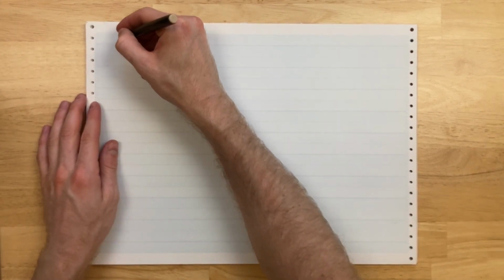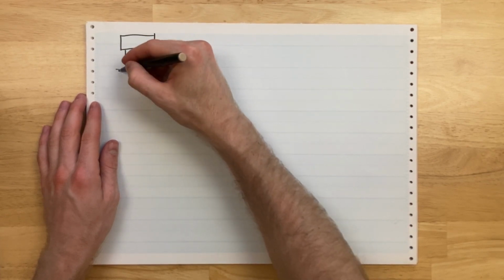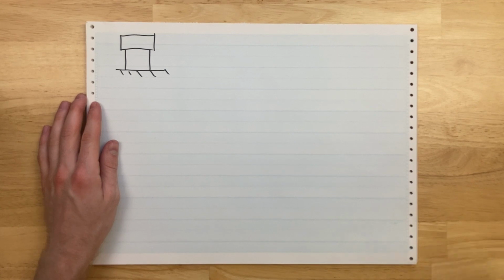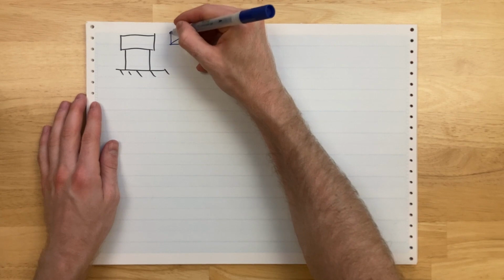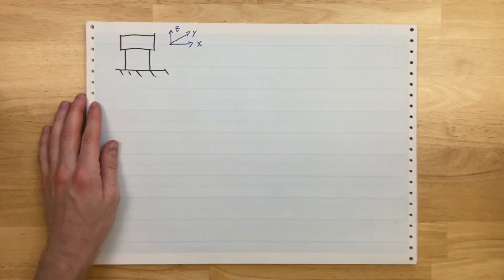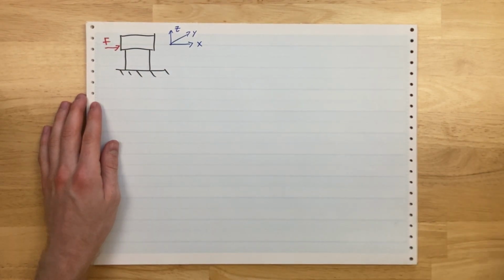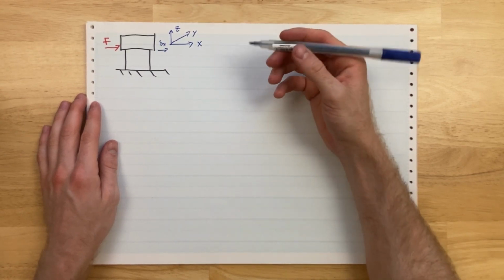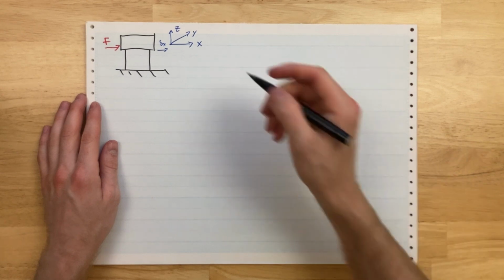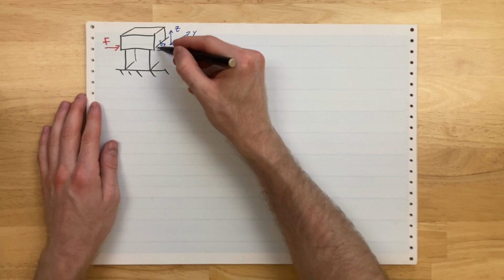So what is the parallelogram flexure? I have a bar. That bar has 2 beams. Those beams are on a fixed base. And I take my coordinate system. It moves in X. Y is out of plane. Z is vertical. And if I push on this with a force F, I find that it will move a distance delta X. And if I look really carefully, or if I actually zoom out a lot, this bar has some thickness to it, and these are rectangular beams.